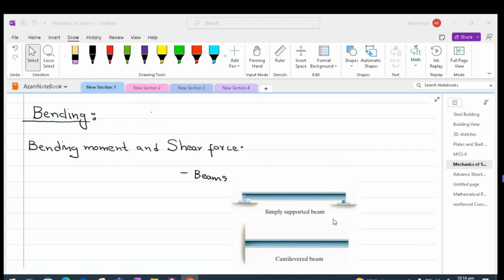From our statics knowledge, we know that whenever some load is applied onto the beam, that load is then transferred to the support. The way we transfer it to the support is by using equilibrium, especially if we have a determinate structure. In other words, if we are able to get our unknown reactions from the available equilibrium equations. Normally, the equilibrium equations are summation of all the moments must be equal to zero, and summation of all the forces must be equal to zero. So if these two sets of equations give us sufficient equations to solve the unknown reactions, then we call those structures determinate structures. In this course, we will mostly be considering determinate structures. So from our statics, we determine the unknown reactions of these determinate structures using simple equilibrium equations.